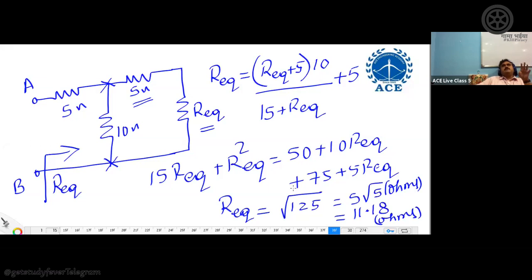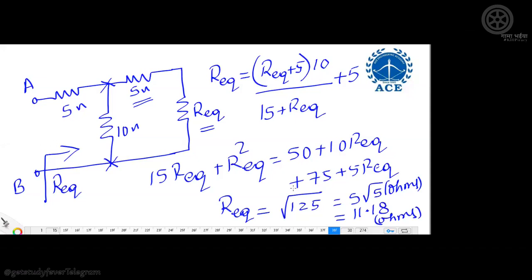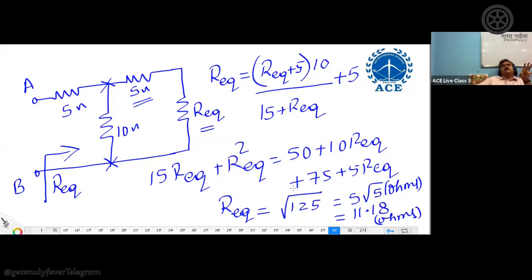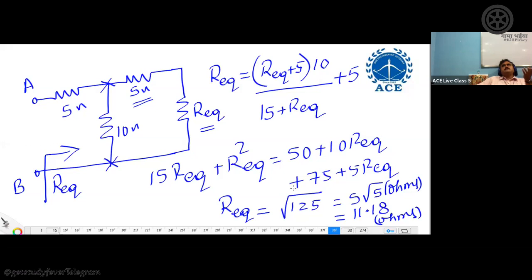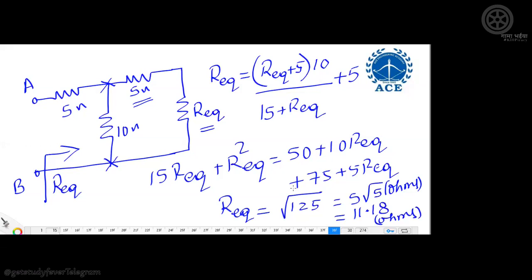So it will be half L. What is the current at 2 seconds? It is 6 amps, sir. Okay, correct. No need to take anything else. Stored or absorbed energies are the same, no, sir? Okay, sir. The inductor will absorb and then store energy up to 2 seconds.